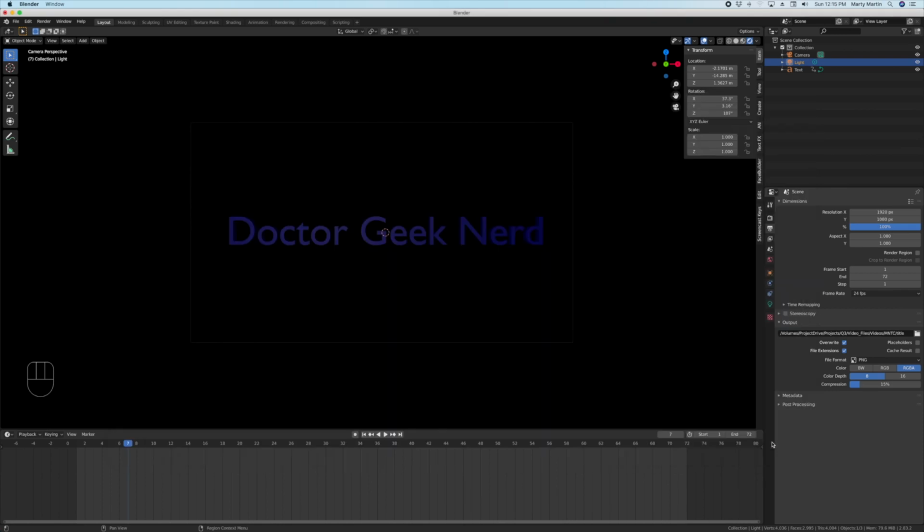If we leave things the way they are now, it will render as a series of PNG images, which is fine. There are reasons why you would want to do that. In this particular case, it's just a simple 3D animation. Not a lot of texture, not going to eat up a lot of computer space, so it should render pretty fast. So I'm going to click on this PNG menu, where it says file format, and it'll give me a drop down menu.